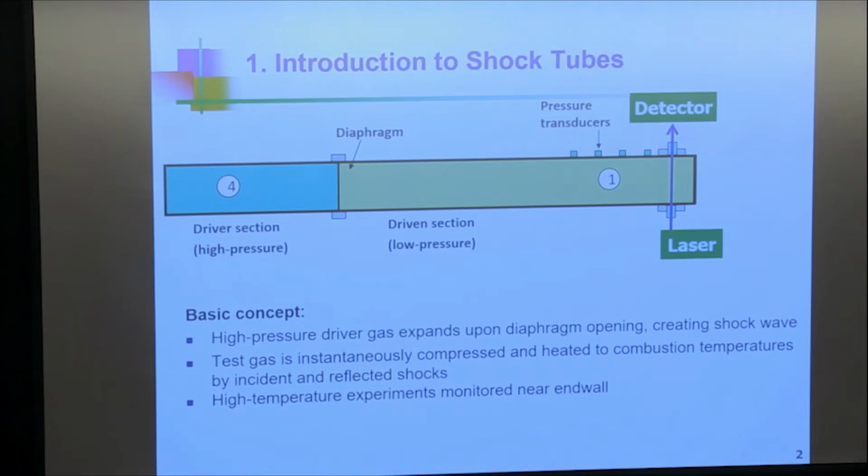So the nice thing about a shock wave is most of the time we can think of it as a discontinuity of 0 thickness. And if you measure the shock speed, you use compressible gas relationships to get conditions on the downstream side.